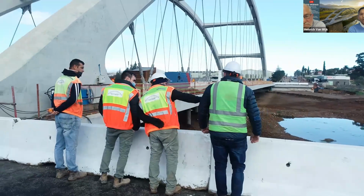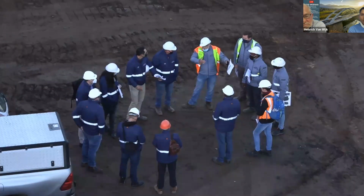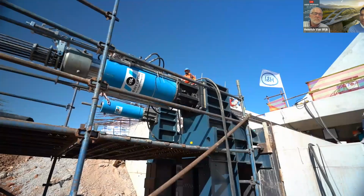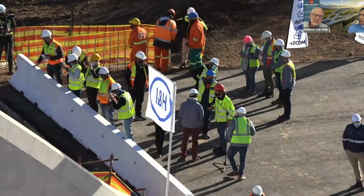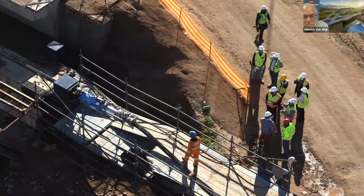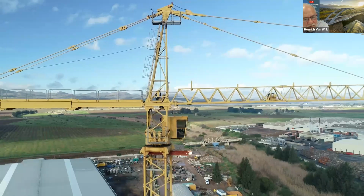So there is quite a comprehensive maintenance manual that's put together for this structure. And I think there are eye holes. You just have to correct me if I'm wrong here, but there are temporary eye bolts connected on the top of the arch ribs, so that the type of abseiling team can gain access if necessary on the top. Yeah, we actually found that